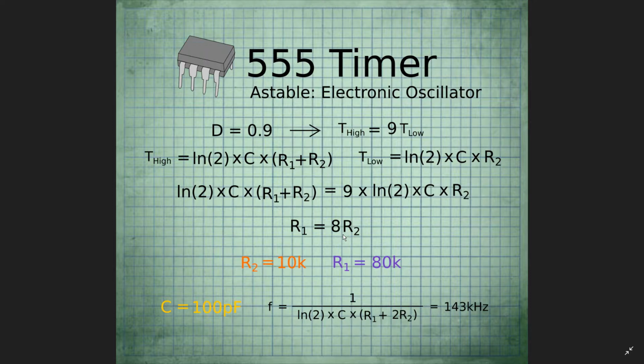There is one caveat when using a 555 timer. The R1 resistor needs to have a power capability greater than VCC squared divided by the resistor value. So the higher R1 is, the more efficient your circuit's going to be, and also the more likely you'll satisfy that power requirement. But it also does change your capacitance value, obviously, because, well, if you look into how a 555 timer works, it makes sense. These will change the capacitance value, and again, they're all linked in the equations.